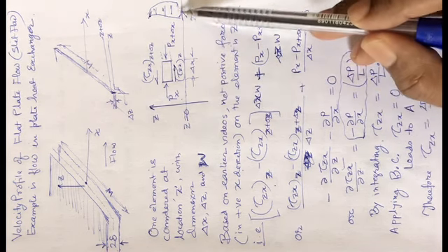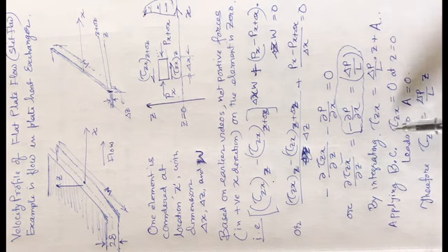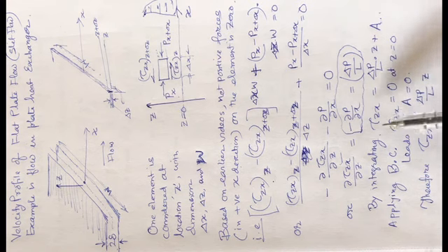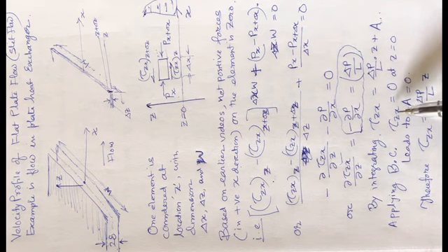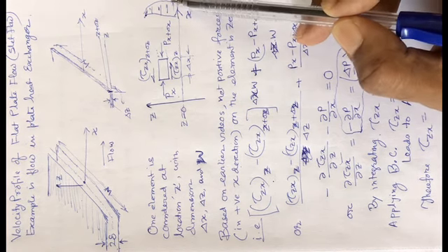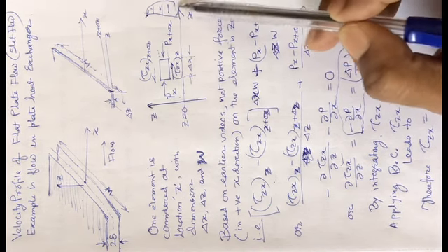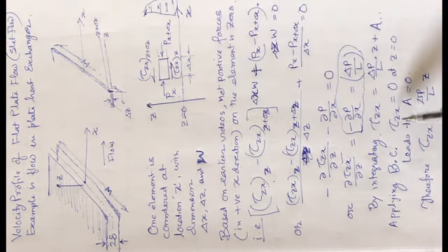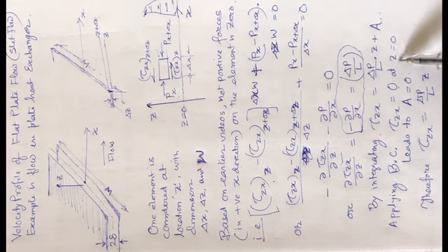So no shear stress means, see, what we will be seeing is that tau zx actually involves one term, the change of velocity with respect to position. So now if we are getting the maximum value here, it means the derivative with respect to position will be 0. So therefore tau zx is 0 at the midpoint when z is equal to 0.